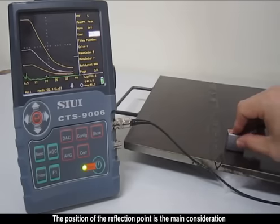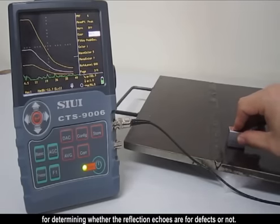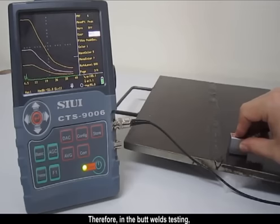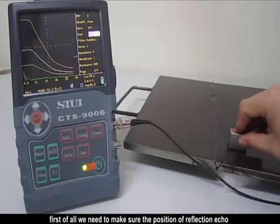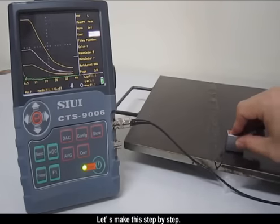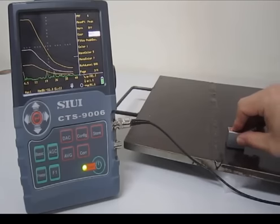The position of the refraction point is the main consideration for determining whether the refraction echoes are for defects or not. Therefore, in the butt welds testing, first of all, we need to make sure the position of the refraction echo and determine whether the refraction point is in the butt welds. Let's do this step by step.